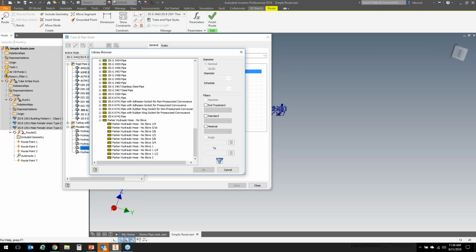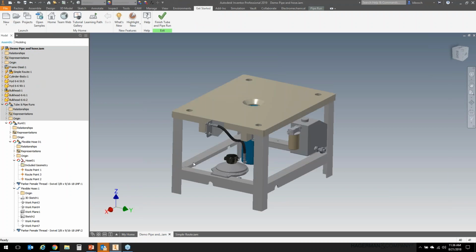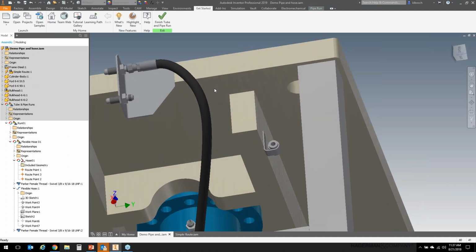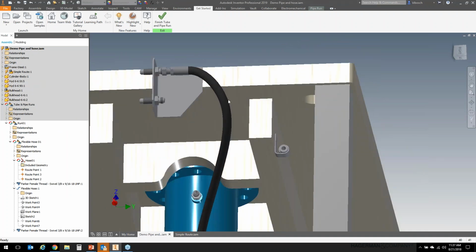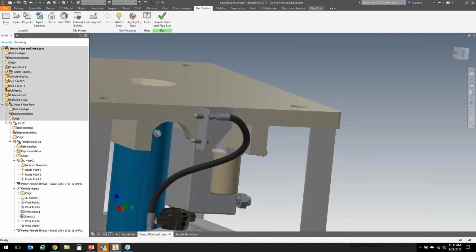Yes, they will. And it depends on that movement and the settings that you've got. As we placed this hose, I had set a defined offset point from this face. So the rules determine that my bend radius has to be within a given radius, and I think that's 1/2 inch on this particular hose.